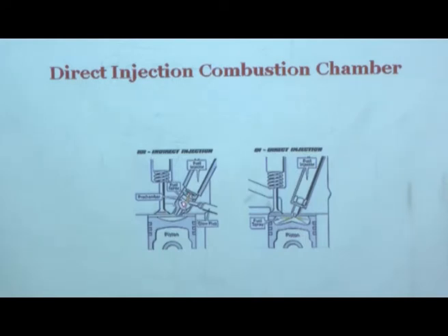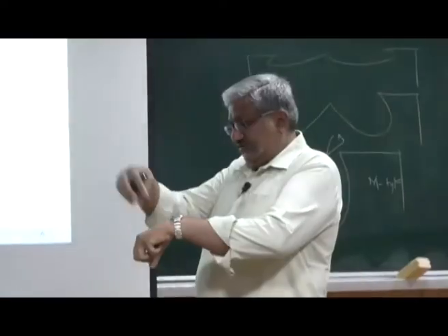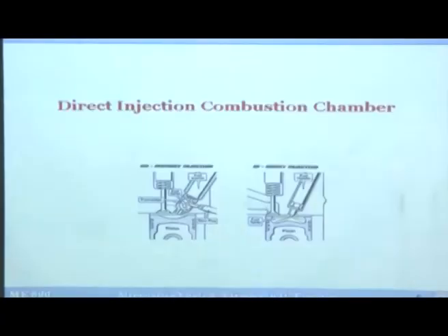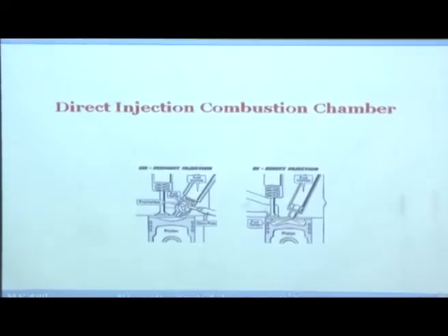Here the single jet is coming out, but you don't want this jet to go directly into the main chamber. So there is a stop here. This is called fuel swirler. Basically it's like a block. You have created an obstruction, the jet is coming and it is not allowing the fuel to go directly. It is stopping here and allowing it to remain inside the pre-chamber. So that's what is shown here. The main difference between DI and IDI is clear. I will come to more details in my next slides. Is this clear?